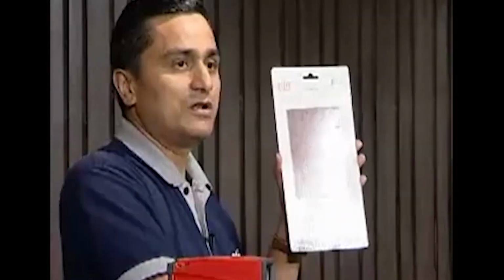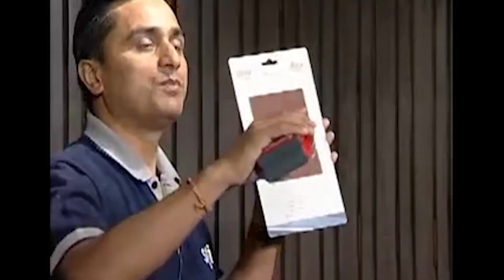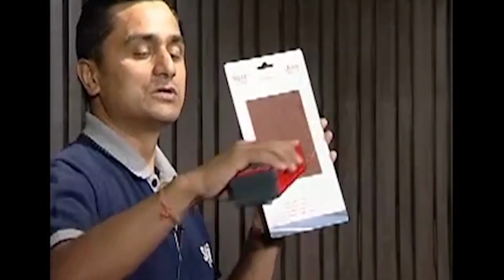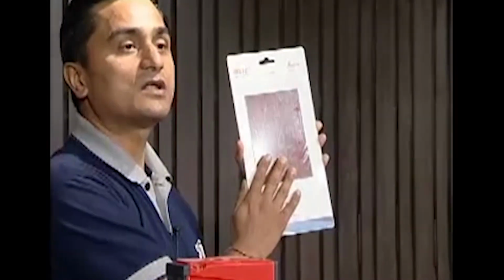Right now when I am using this instrument, for example in this case, I am pointing there. Now here in this case, what is happening, the reflection is coming from the wall. So our target is the natural target. We are not using any external target. However, we can use some external targets also. For example here, this is a material which we say retroreflective. This will reflect the laser pulse in a better way. So sometimes when the distances are large, we use this as the target.